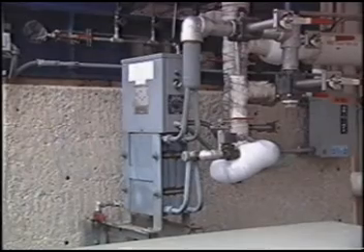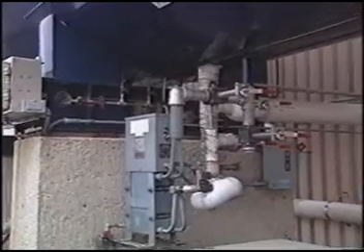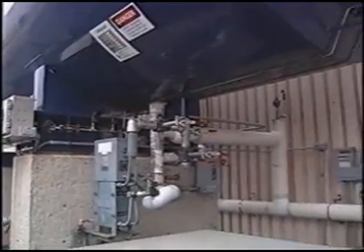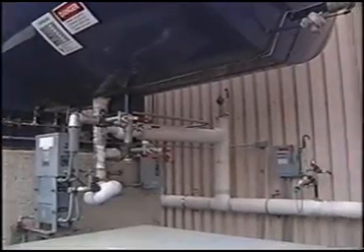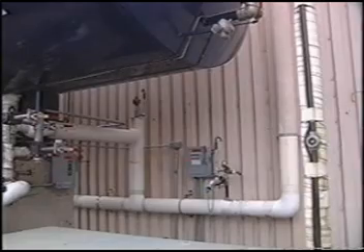Pipelines carrying liquid carbon dioxide have a vaporizer between the tank and the pipelines that changes the liquid to a gas by warming the cold liquid carbon dioxide. Make sure the vaporizer is large enough to prevent any liquid from passing through, even at the highest demand rate.